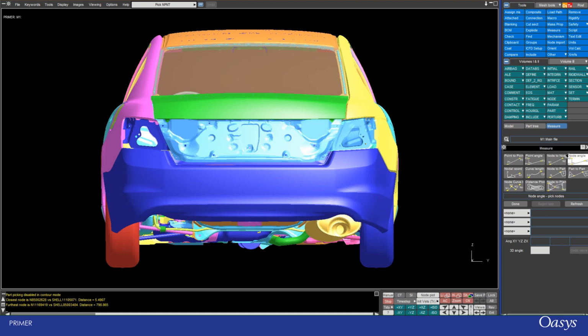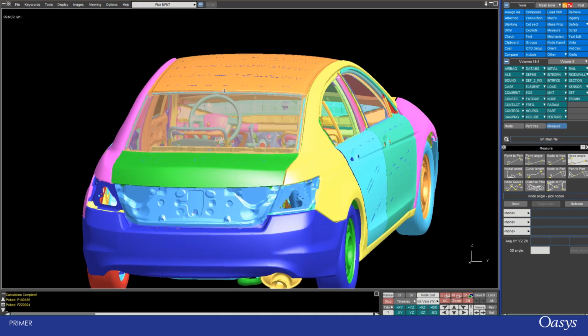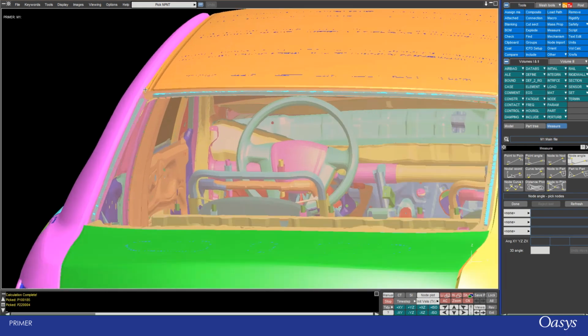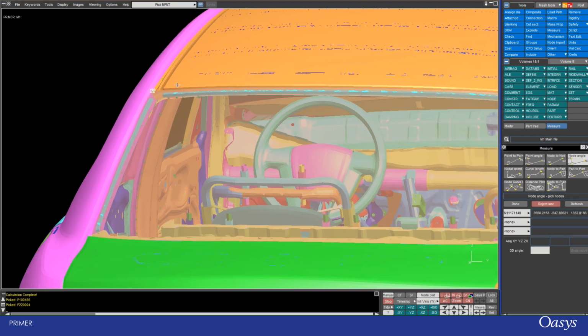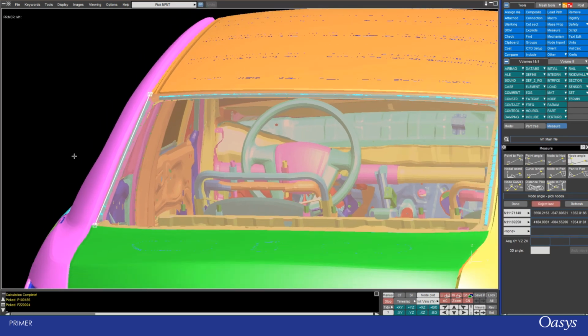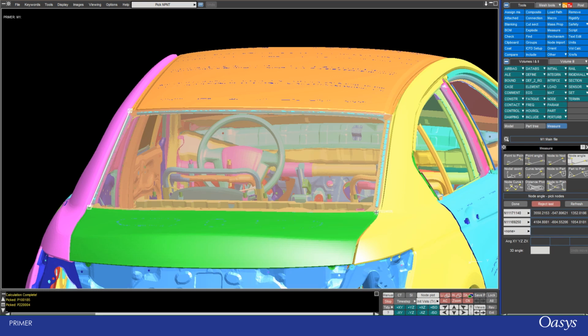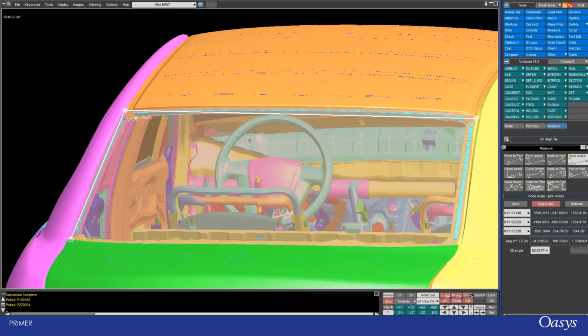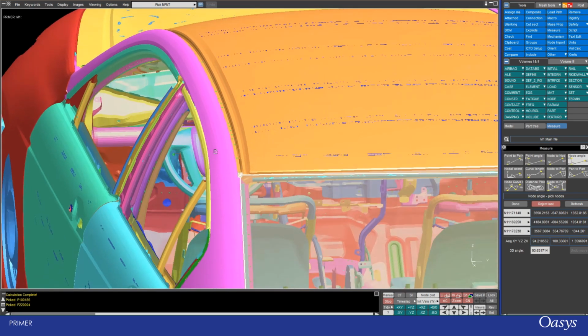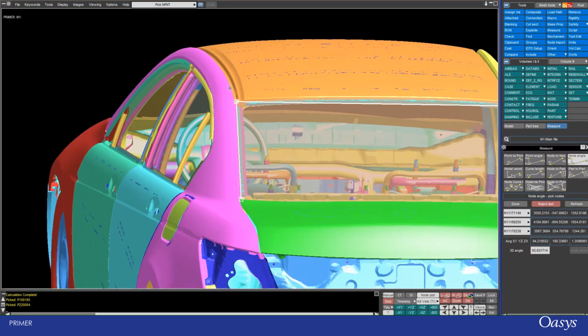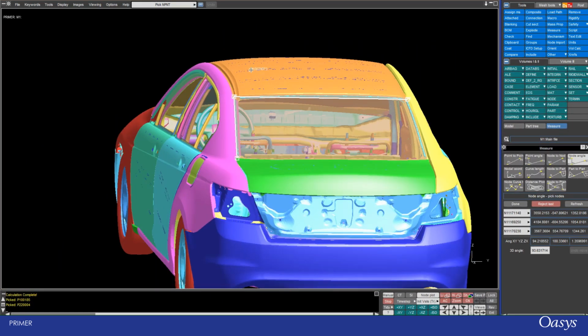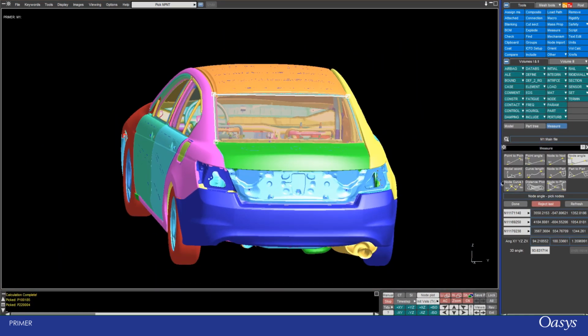Then we've got node angle. So you can do something similar with nodes, but this time it's fixed to a specific space in the model. So if we were wanting to measure, say, the top of the windshield at the back, down to the bottom, and across here. Let's go here, because remember the first node we select is the middle. And that's about 93.6 degrees. So that's about what we'd expect, approximately a right angle there.